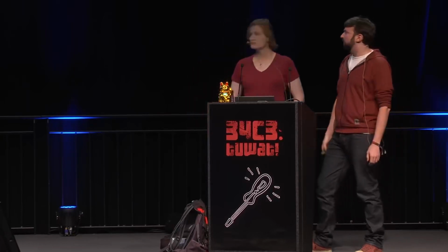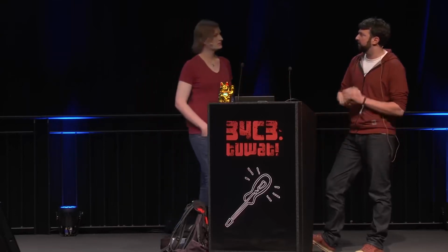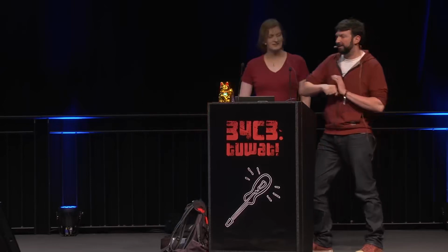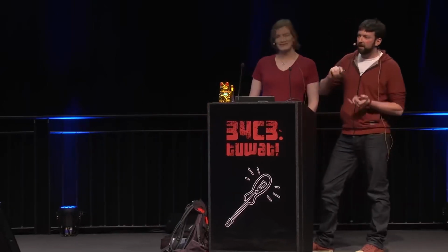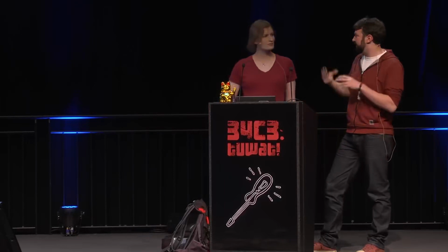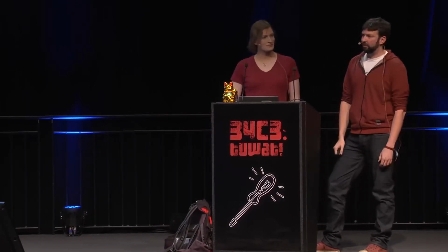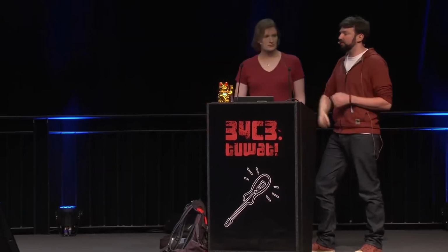Something like that. UART, I don't really want to talk about UART because I implemented it and it currently doesn't compile. But UART is not surprising. It's a pretty common debug interface that you're going to find. If you tear open one of those standard routers that you get from your ISP, it's going to have a serial connection on it, and you might want to use that to work out when its bootloader has started up, because it will dump some information.